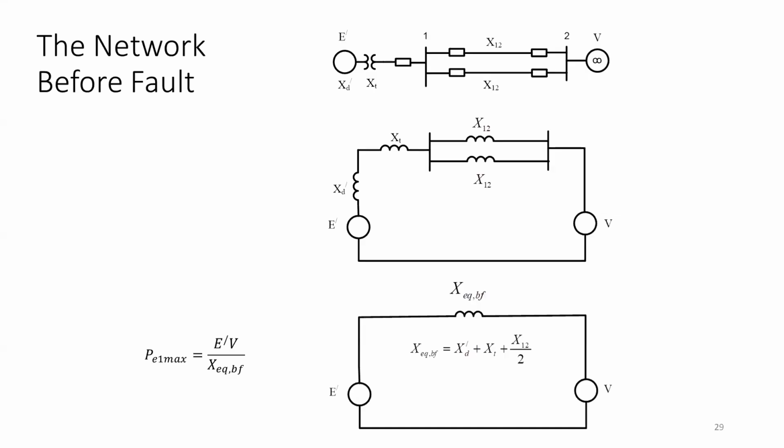Getting back over here. How will your network look after fault? Can anyone tell me? Sir, there will be only E dash, XD dash, and XT in series.